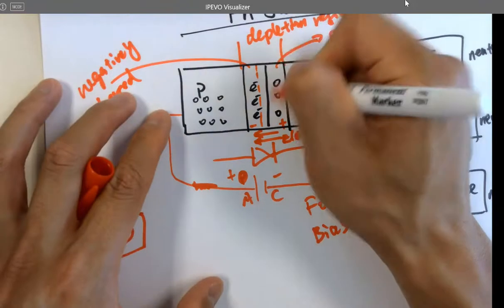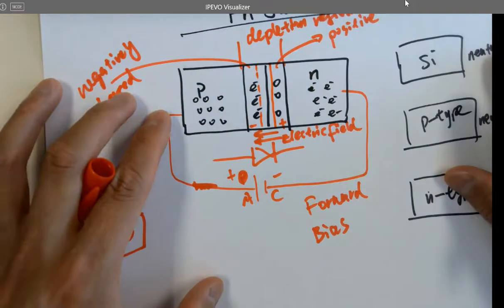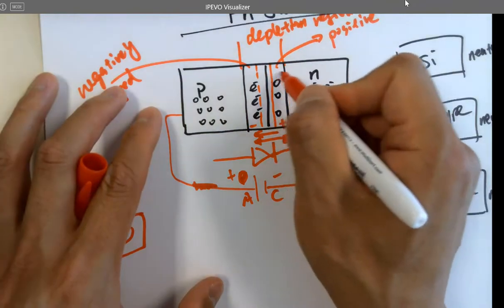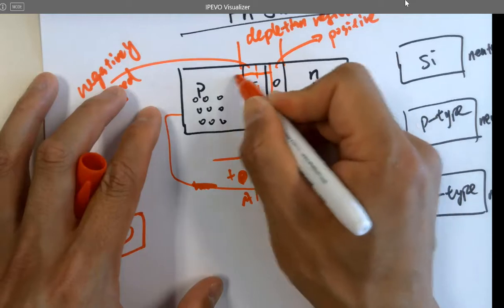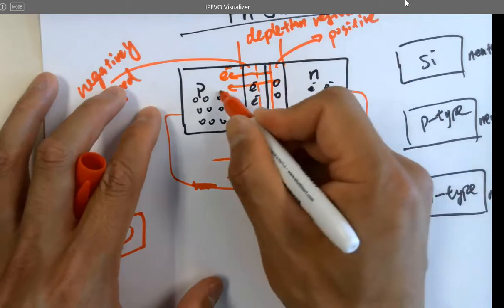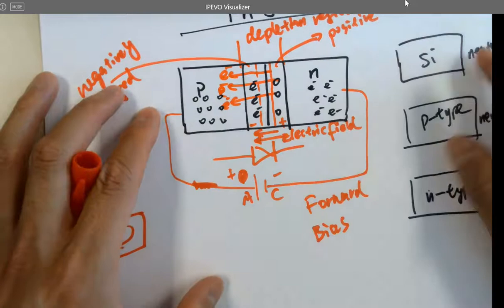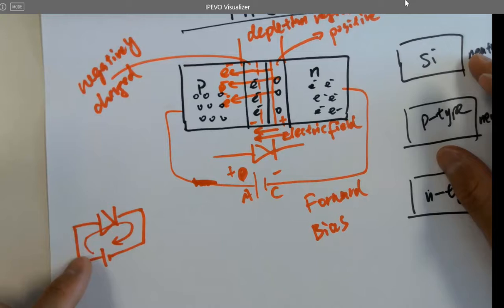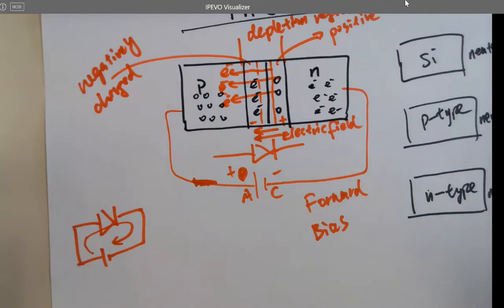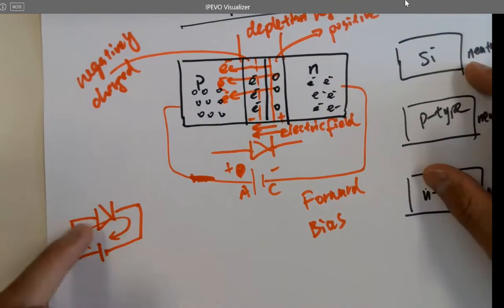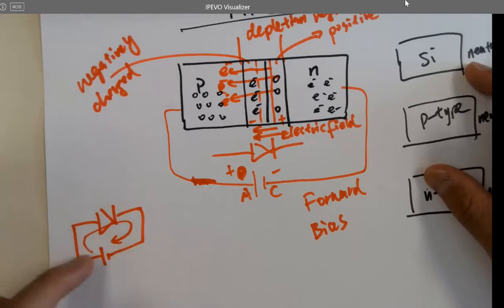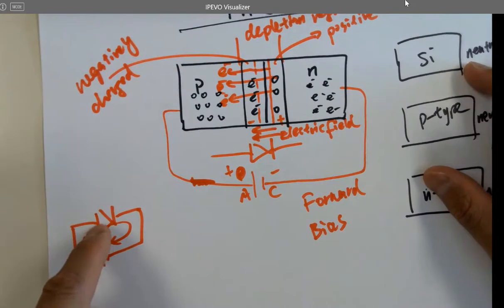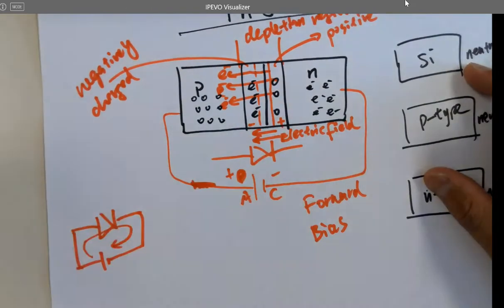Whenever it's thin enough, what's going to happen? The electrons, you are getting more electrons here to tunnel through, like a stream of electrons flowing that way. And what's happening? The diode becomes conductive. It passes the current like a short circuit, freely flowing the current in the circuit. That's what's happening here if you connect the diode in forward bias in the circuit.